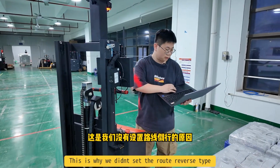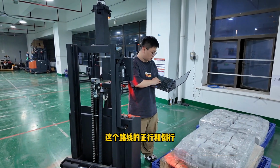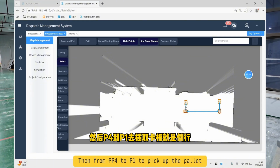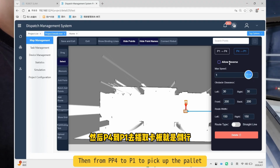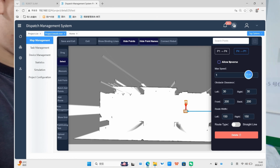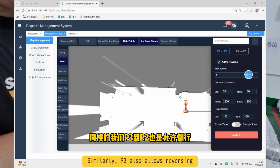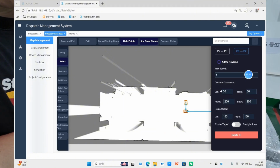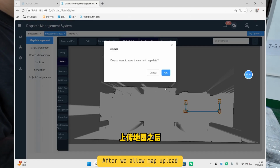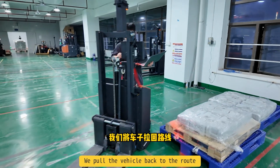This is why we didn't set the route reverse type. We first need to set the forward and reverse types of this route. For example, P1 to P4 is forward type. Then from P4 to P1 to pick up the pallet is reverse type. Click to check, allow reversing. Similarly, P2 also allows reversing. After we allow map upload, we save it. After saving is finished, we pull the vehicle back to the route.